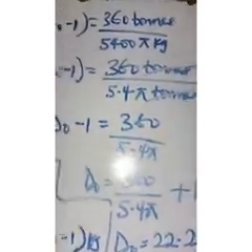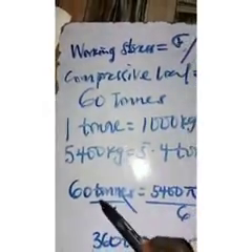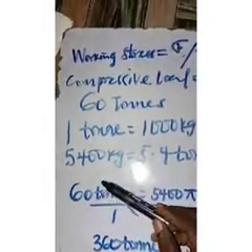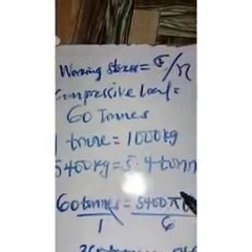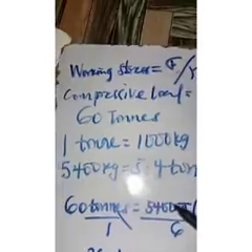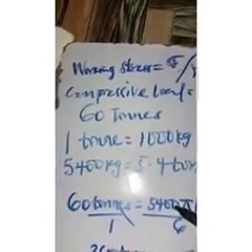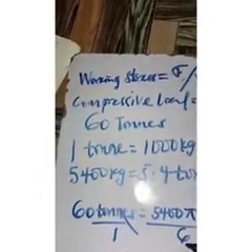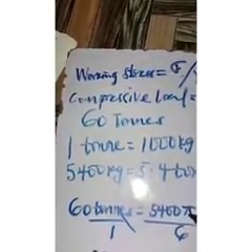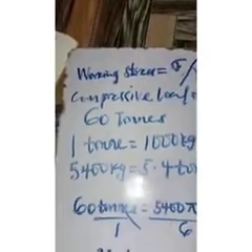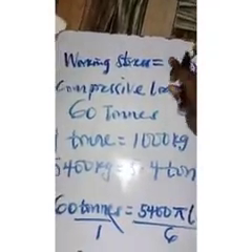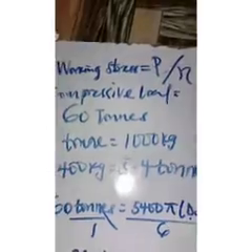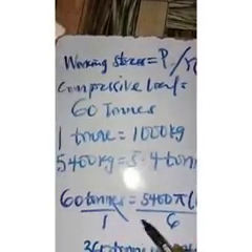Also I explained that from here you can have your working stress as this, your 1 ton is this. From there we can put the formula, that is the compressive load or safe load is equal to this, that is your P. Remember, your P is your crushing load, because your crushing load over safety factor, if you remember the formula like that. You can apply this, or you can simply say this in case it's confusing. You have that, and that will be this. So I put this guy here.